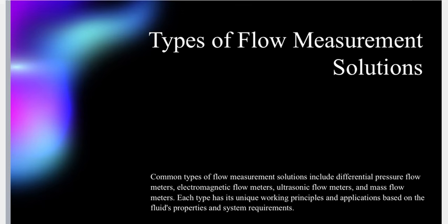For the advantages and disadvantages: the advantages are that it is proven and reliable technology, it can develop from time to time, it is easy to install, and works in harsh conditions. With the disadvantages, it causes pressure loss, and the accuracy depends on the fluid properties. You should know the properties of the fluid before starting to measure the flow of that fluid.